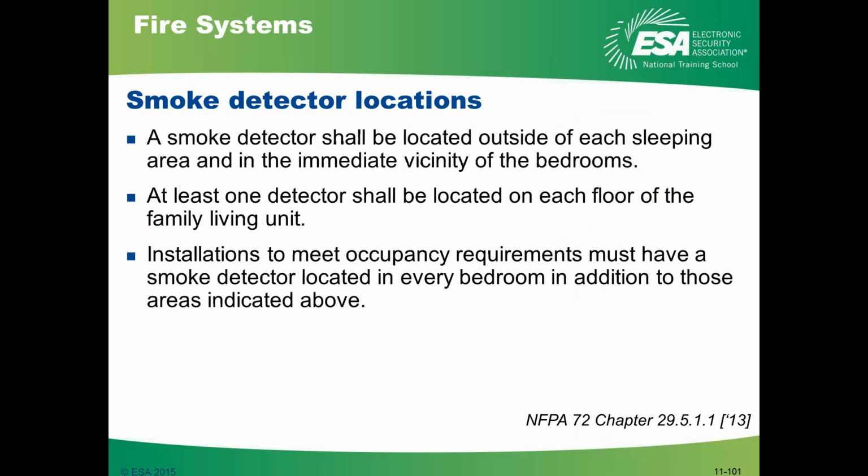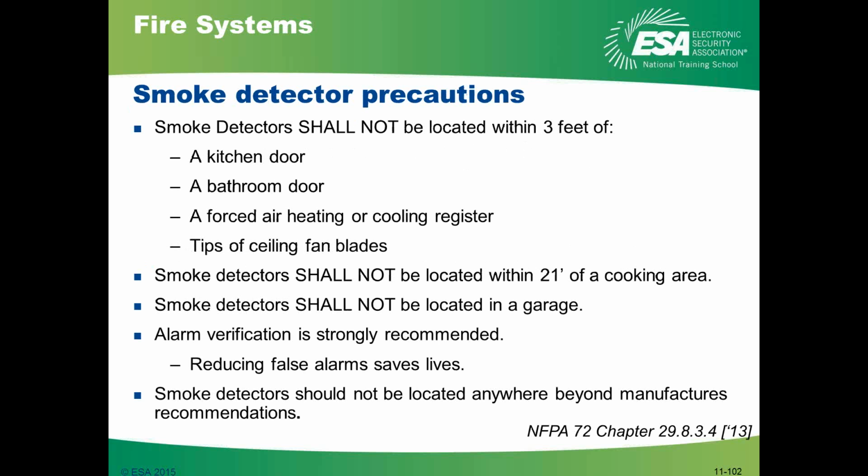These are locations. This is also not just in 72, it's also in the building code. A lot of the countries now under the IRC, and this is also located in the IRC, the IBC, and 101. So it doesn't matter which building code you're under, everyone in the nation has these requirements where there are detectors outside of each sleeping area, in immediate vicinity, on each floor, etc.